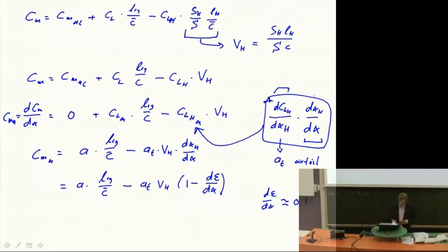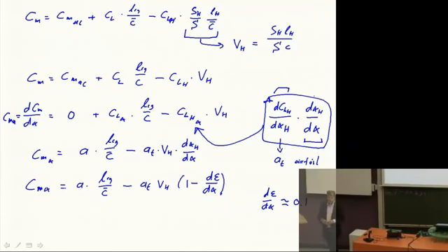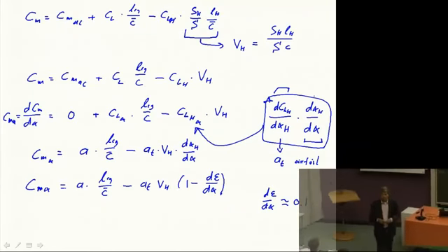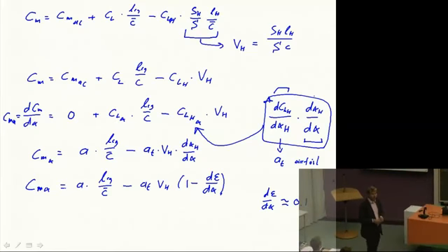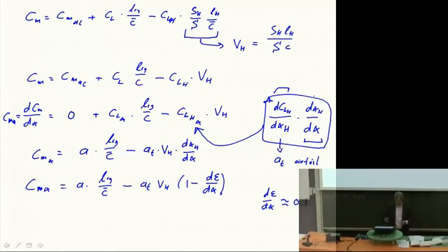So this is the CM alpha. So what kind of CM alpha did we need to have a stable aircraft? Because that's why we started this whole derivation with all the CM alpha and stuff. We wanted a statically stable aircraft. And that we translated to a certain property for the CM alpha. It had to be smaller than 0, negative, exactly. So let's look at the border case here. If it has to be smaller than 0, we need this to be large or this to be small. Right? If we want CM alpha smaller than 0.